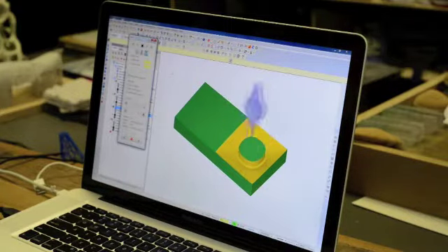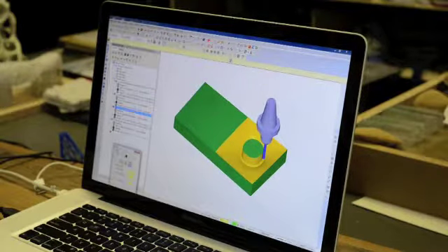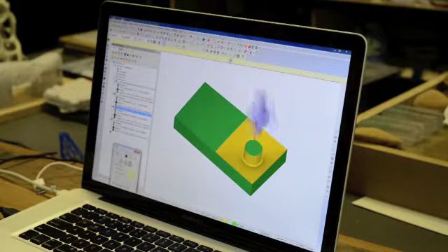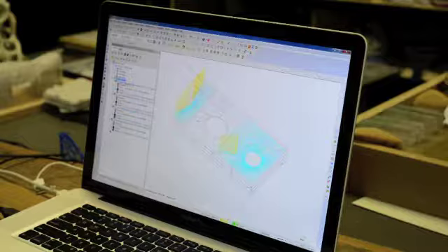And you can see actually it's just doing the finish pass because that was the only thing that was checked off. So you can just click on each one individually, or you can click on the group itself, and you'll see when you do that that they're all selected. And you can turn toolpaths on and off individually. So if I click on this first folder, you'll see where it says toolpath, and it gives you the amount of data.